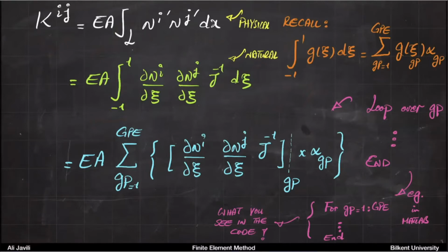Now, it turns out if you had a two-dimensional finite element method, formally you would have the same thing. I cannot jump to that now. We need to basically go through the mathematical steps and derivations for that. But what you will have eventually is, again, some sort of a stiffness matrix with its components being related to the derivatives of shape functions, but now shape functions would be in 2D.